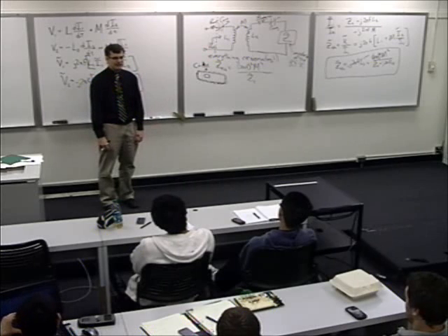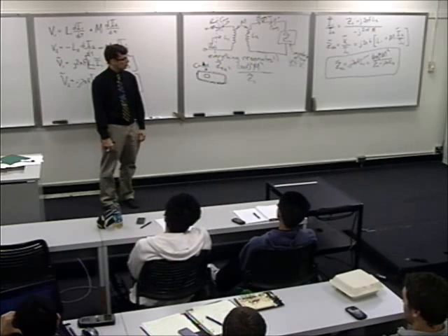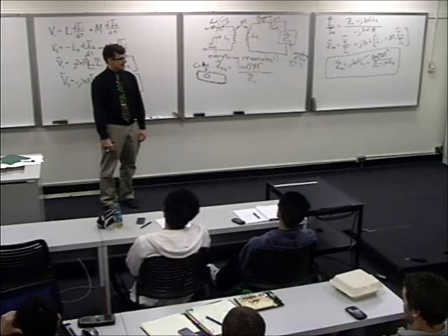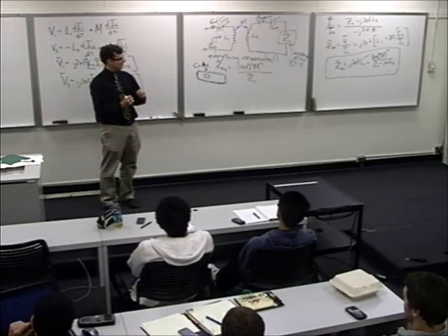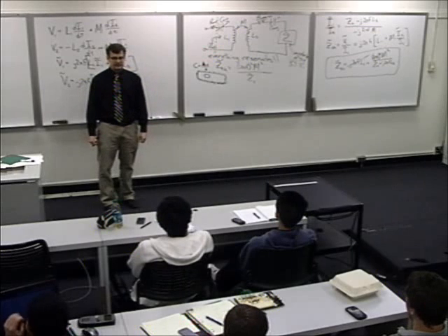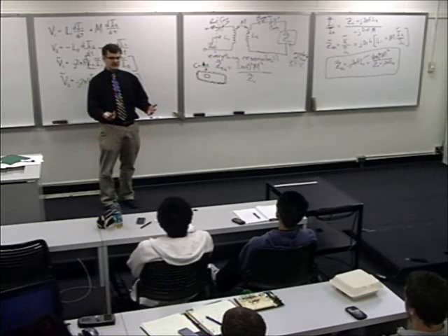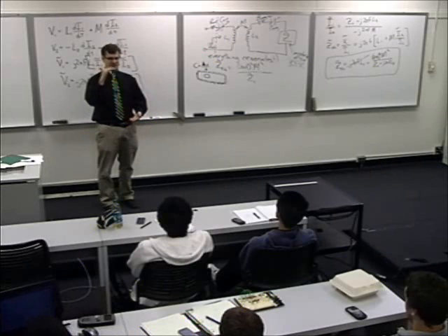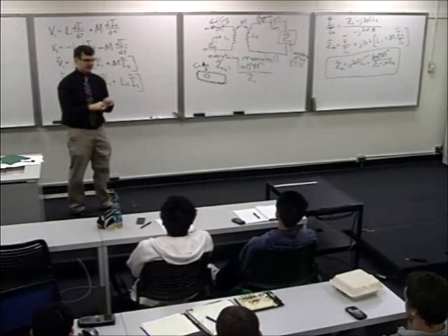So that's probably not a very good way to do it either. You could put an active amplifier on your tag, and thereby make it, with a little coin cell and some clever electronics, you could make that Z sub L look bigger than it really is. Reflect more power that way. That's another way. That doesn't do good for the sniffing problem, because if you want to sniff at a distance, then usually you're limited by the signal to noise ratio, and if you put an amplifier on there, you wind up amplifying signal and noise commensurately, and then adding some extra noise in. So you never get any better.